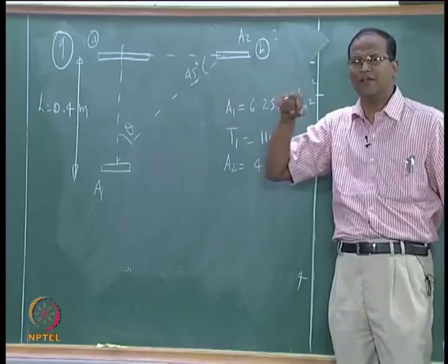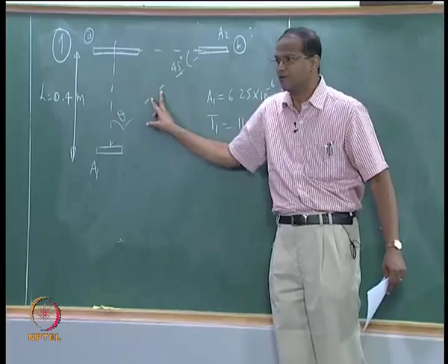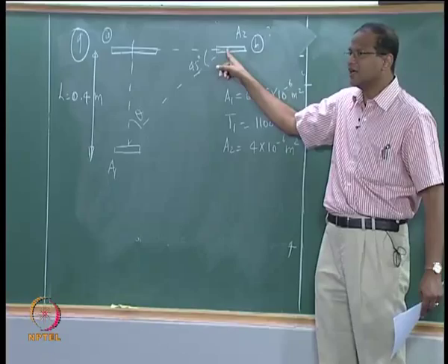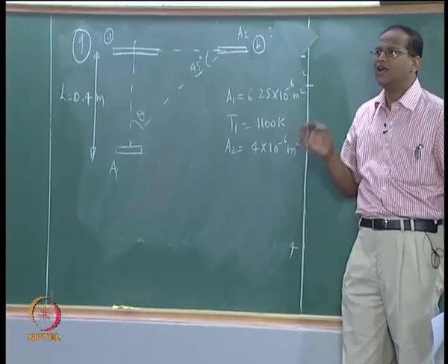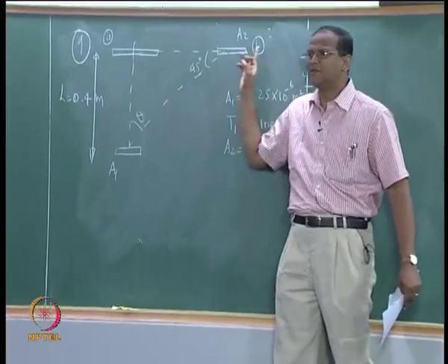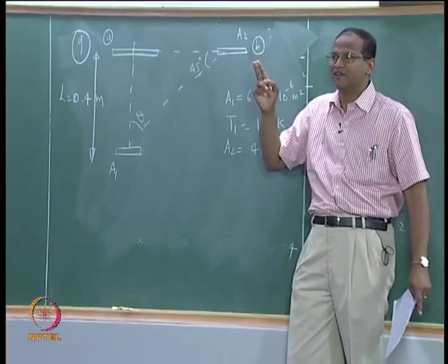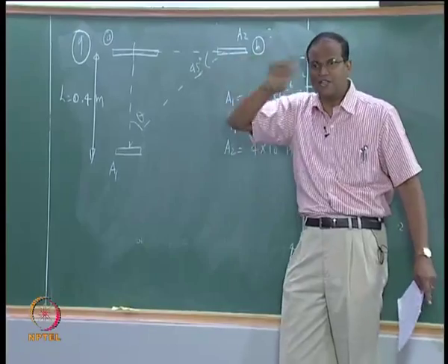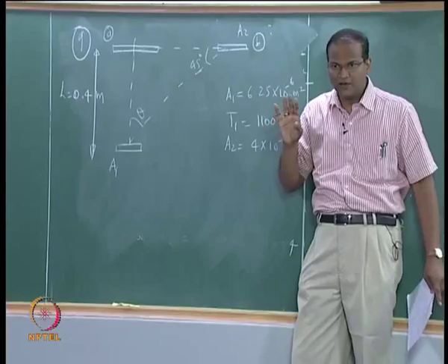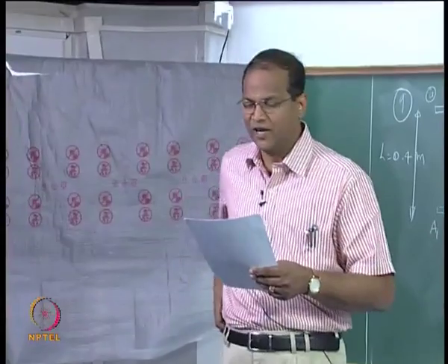Now the d omega, A1 cos theta d omega will become dA2 cos theta by r squared, all that. The r is also changing from the earlier value. Suppose I give you the power, then you can also calculate the emissivity at the new position, and you can take a call on whether this is a diffuse surface or not. If the emissivity in position A is different from the emissivity in position B, then it is not a diffuse emitter. But if it is the same, we do not know whether it is the same in all the directions, but at least you can say between 0 and 45 it is having the same. Are you getting the logic? Now I will give you the data, you can take down the problem, okay. Consider an arrangement as shown in the figure to detect radiation.